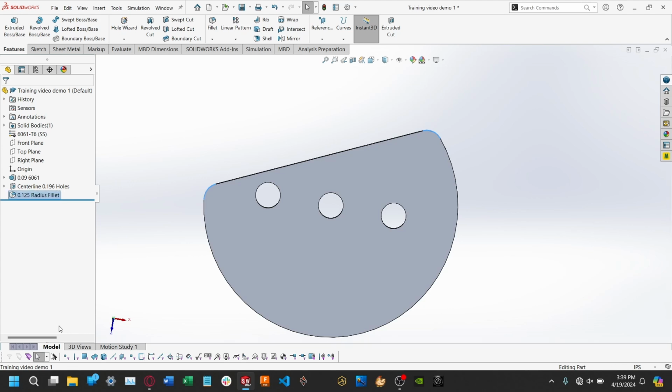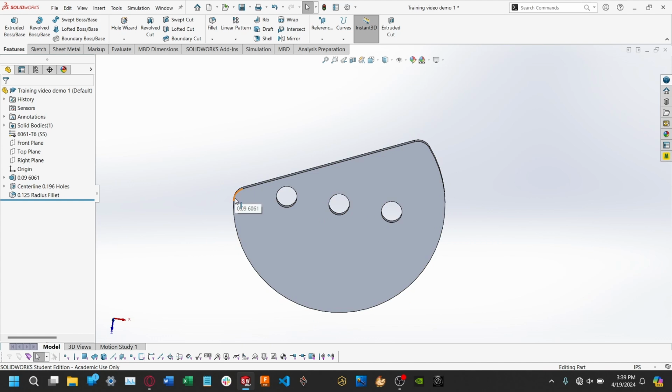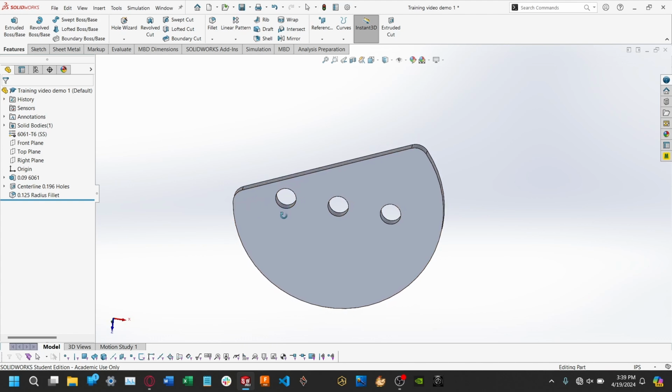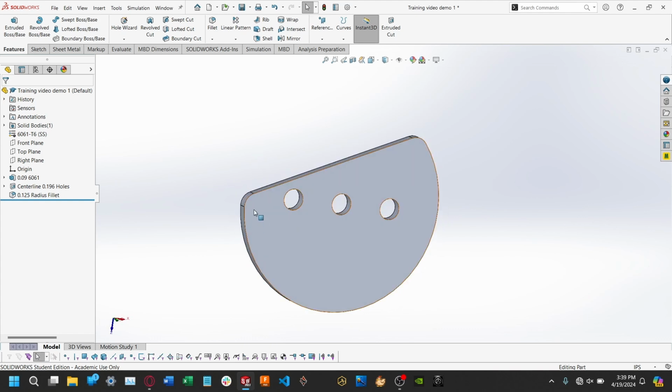This is because our machines cut using a circular bit, which can't make itself infinitesimally small and cut a 90-degree angle. Like, even a laser cutter can't do that. That laser has a really small radius. No conventional machine can do that. So that's why we have fillets. This part didn't have any interior angles, but it did have exterior angles. So those have been filleted to a radius of 0.125.